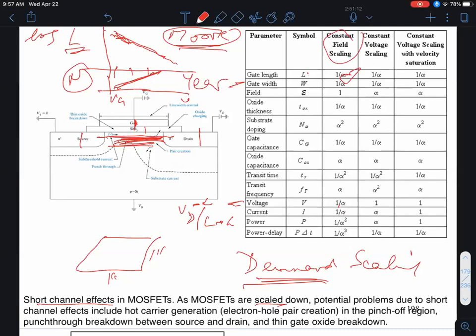Unfortunately, circuit designers are a very stubborn bunch of folks. What has happened in practice is, as technologists have reduced channel lengths gradually from one generation to the other, the power supply voltages have not reduced continuously. Instead, for many generations in ICs, the power supply VDD was kept at, say, 5 volts, while channel length shrunk.